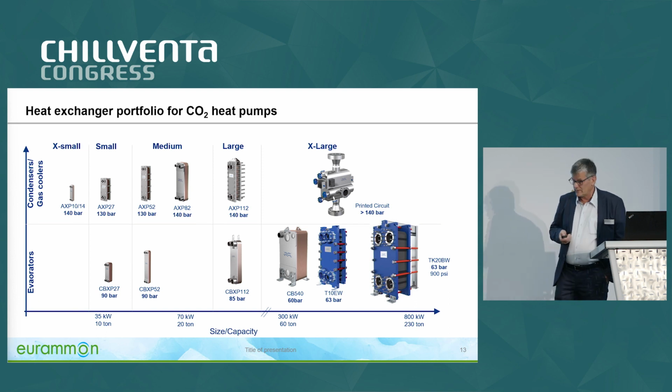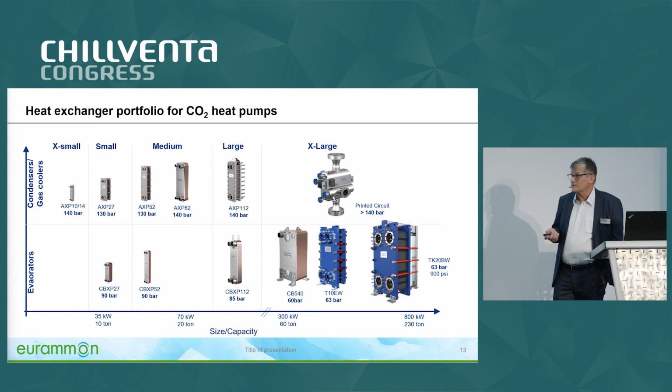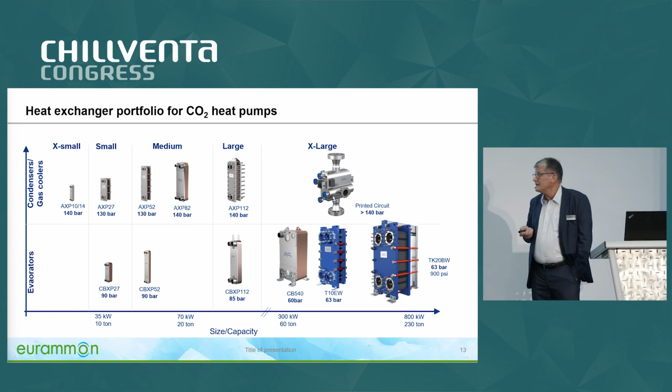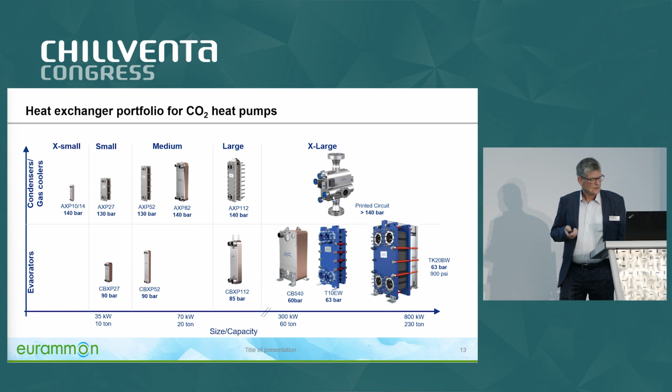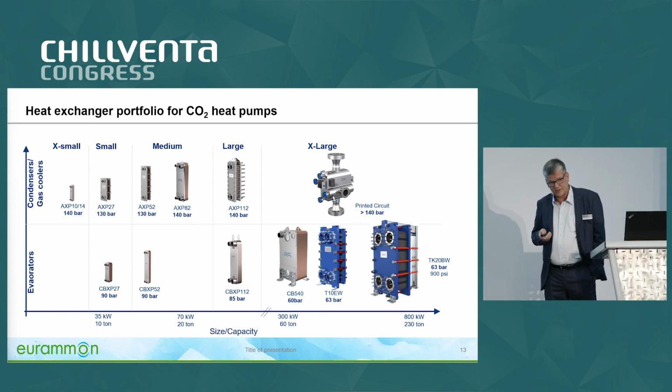For CO2, this is mainly for smaller heat pumps, but also growing now up to some 1 megawatt with different technologies of plate heat exchangers. Of course, taking care of the higher pressure need for the condenser side.